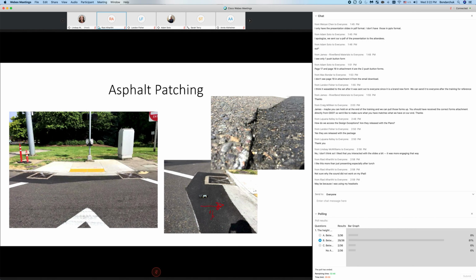So as you're pouring the asphalt to build the new ramp, you construct the ramp, and you come back with a patch here, and then you slope it up too fast, worse than the existing condition, it will fail. It should not be more than 5%, and should not be worse than the existing roadway slope across the slope. So make sure that as contractor and inspector you check this one out.